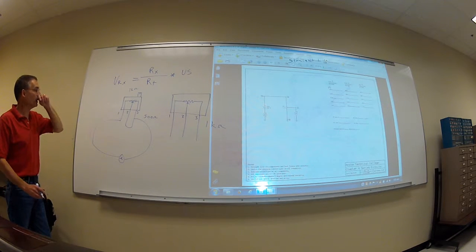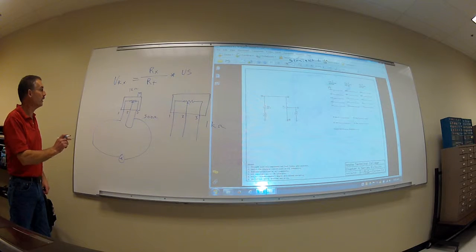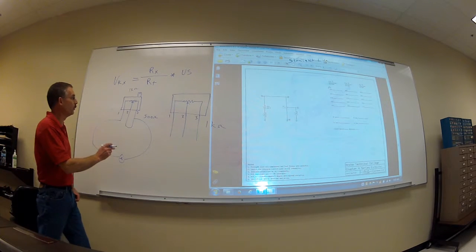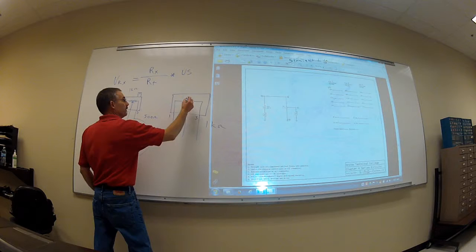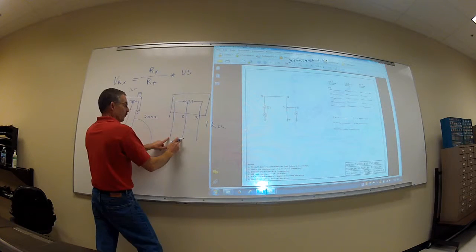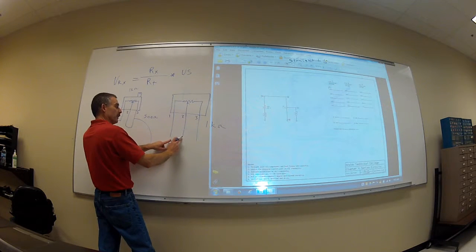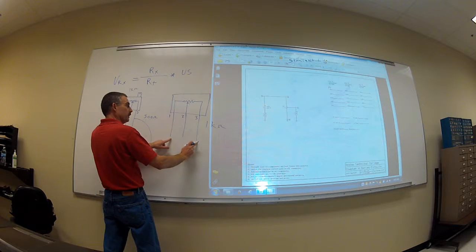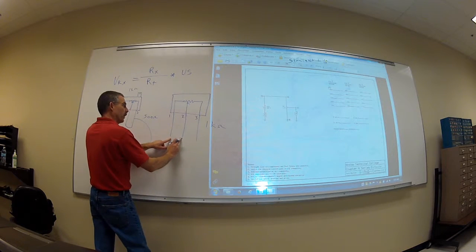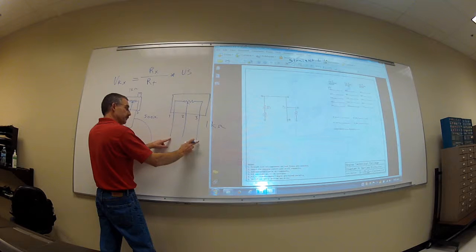And then another one was that it was getting flipped around. Even if I got it set at mid-range here, across pins 1 and 2, I'm still going to get 500 ohms, but from pins 1 and 3, I'm going to get 1 kilo ohm. Okay? So here I would be correct, but here I would be incorrect.